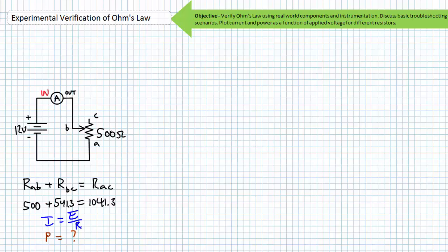Ohm's Law states that current is equal to voltage divided by resistance, 12 volts divided by 500 ohms. We'd expect to observe 24 milliamperes of current. If power is equal to voltage times current, 12 volts times 24 milliamperes yields 288 milliwatts, well inside our desired power dissipation rating. Now, well armed with expectations, we are not just bebopping into an ambush.